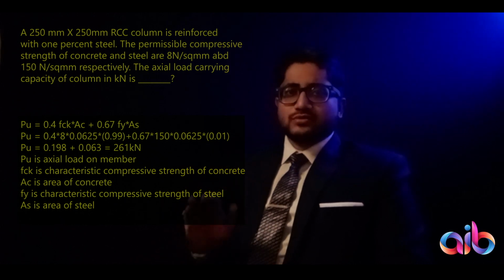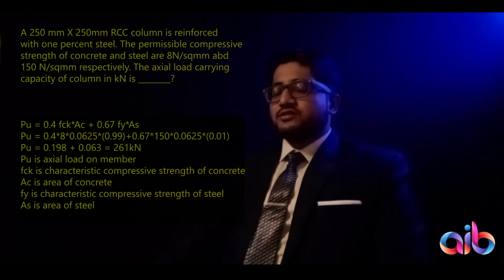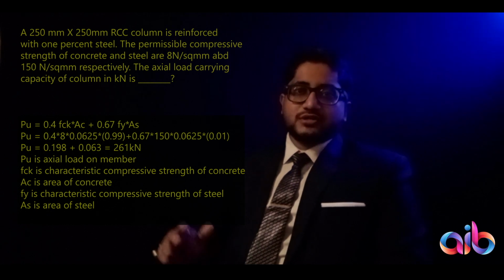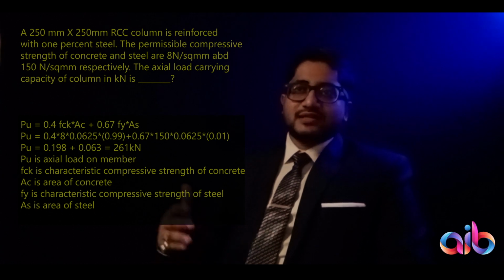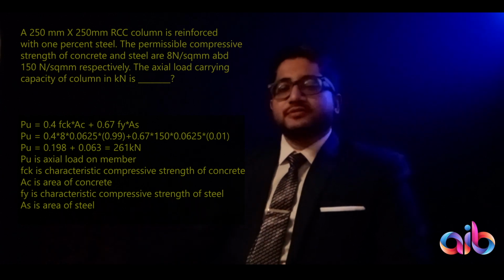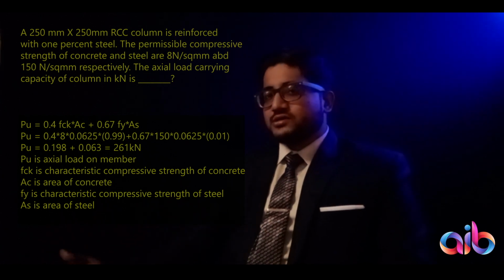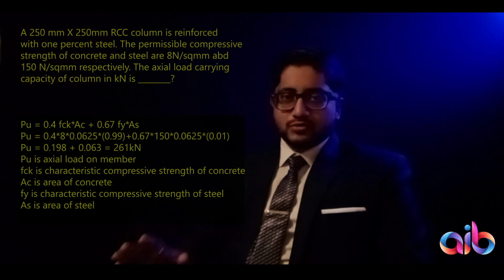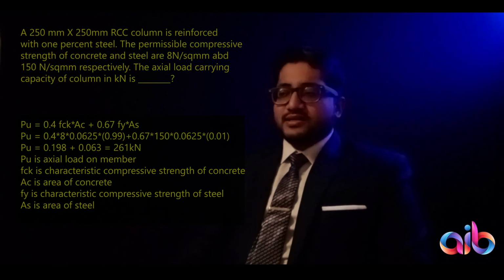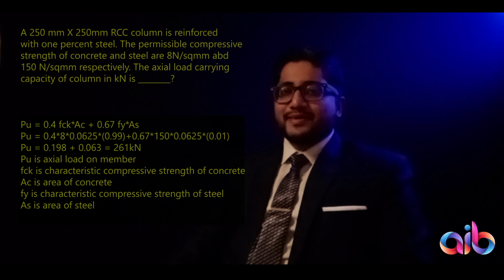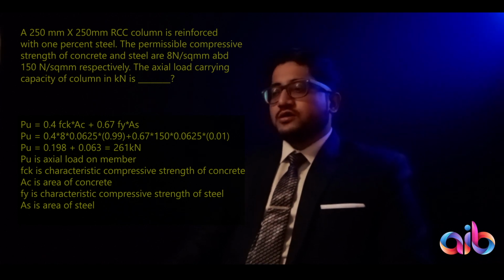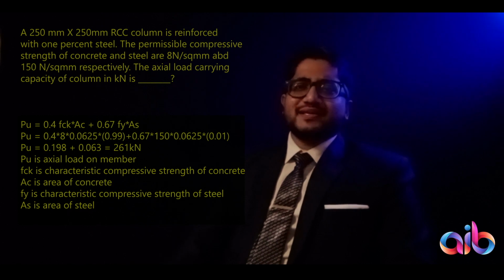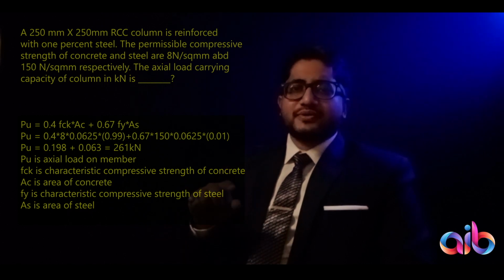As per the IS code as on date, the maximum steel you can have in a composite bar is 4%, because otherwise, let's say you say the amount of steel in the composite bar is going to be 99%, so just 1% concrete, so it turns out to be a steel beam, so that's not possible. So the Indian Standard Code mandates that the maximum it can be is 4%. So here they have given 1%, so it means 99% concrete and 1% steel.